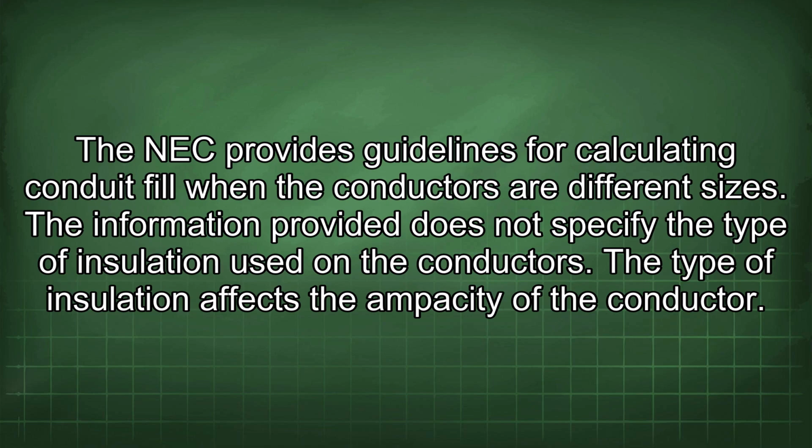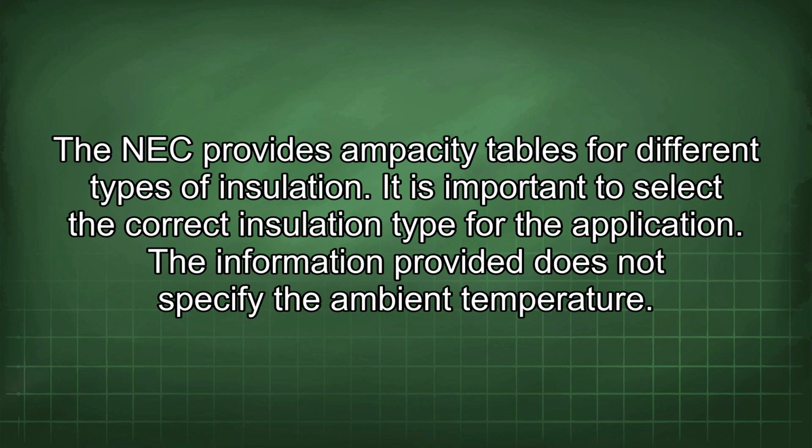The information provided does not specify the type of insulation used on the conductors. The type of insulation affects the ampacity of the conductor. The NEC provides ampacity tables for different types of insulation. It is important to select the correct insulation type for the application.